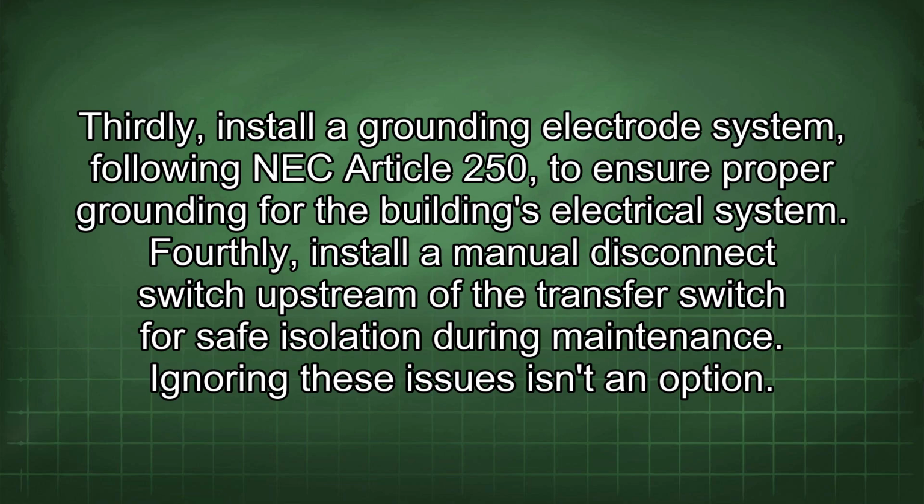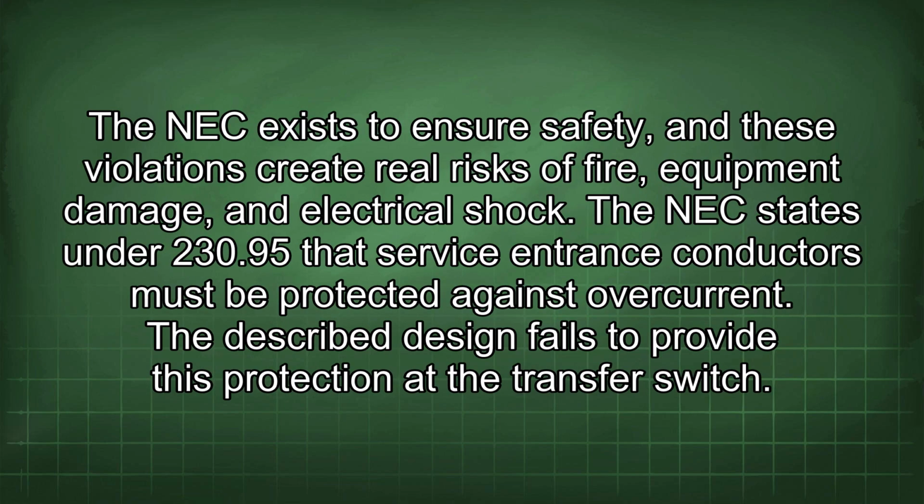Ignoring these issues isn't an option. The NEC exists to ensure safety, and these violations create real risks of fire, equipment damage, and electrical shock. The NEC states under 230.95 that service entrance conductors must be protected against overcurrent.